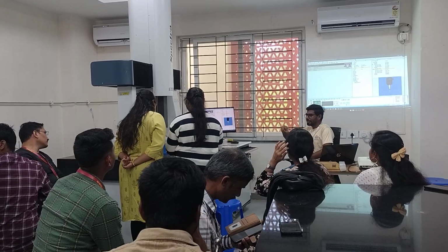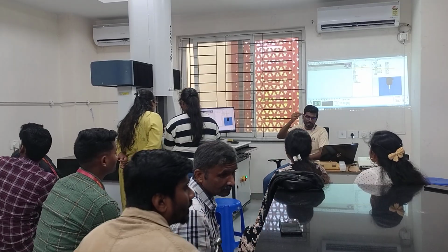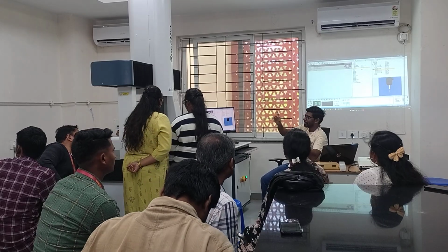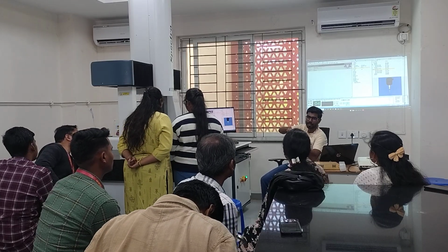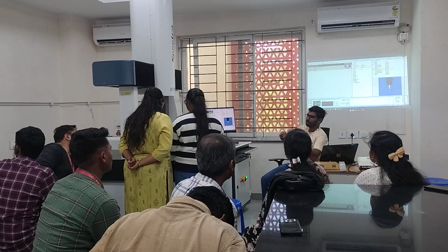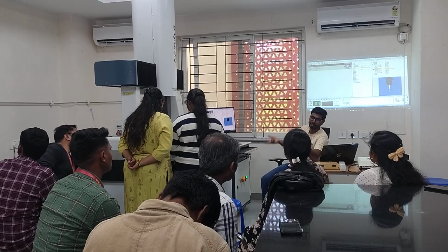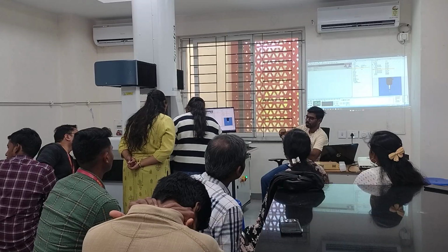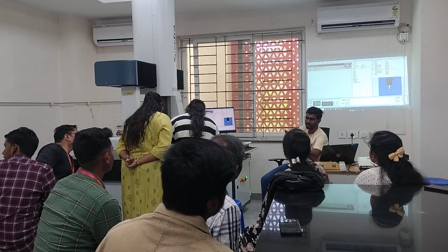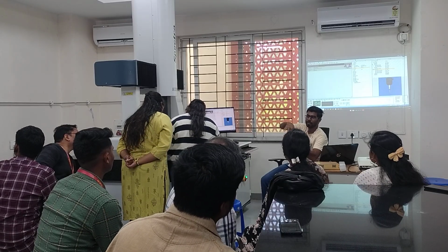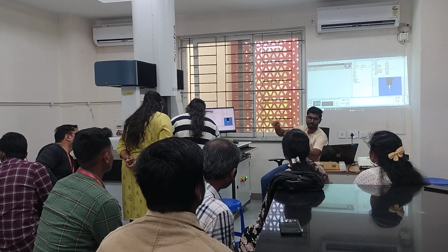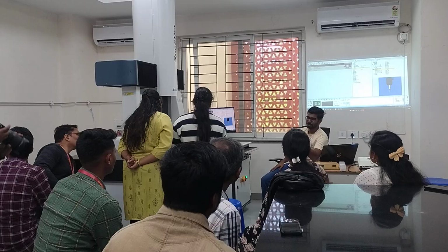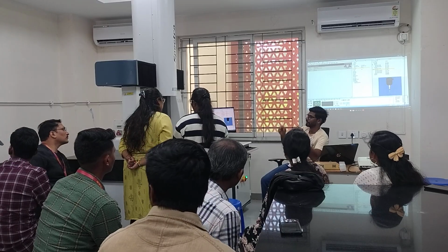So the second part: we are measuring again and again. What happens is there is another feature. If you directly import this CAD model into this, it will automatically understand where other features are, and will program it in a manner that wherever you are doing it manually, it will automatically generate CNC codes. Just place the part there, tell it through 3 or 4 probes that this is my plane, this is my plane. Automatically all the planes, whatever measurement we are giving, it will measure and give us the report at once. So no need to repeat it again and again manually.